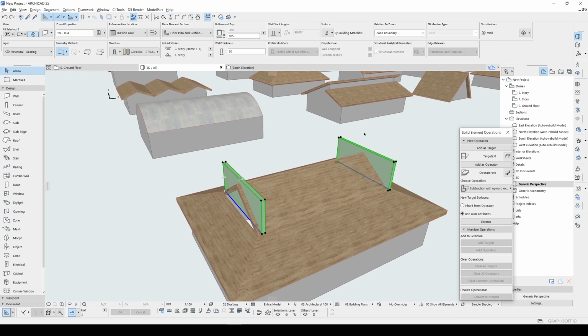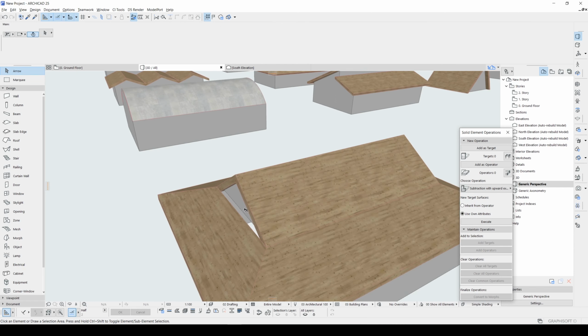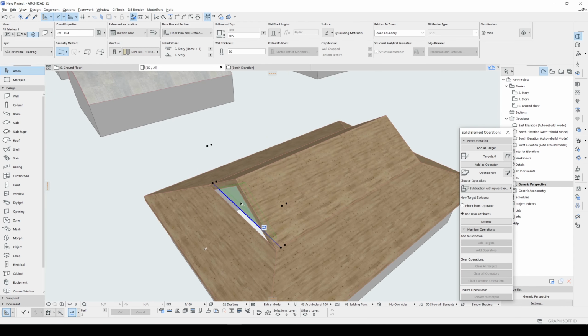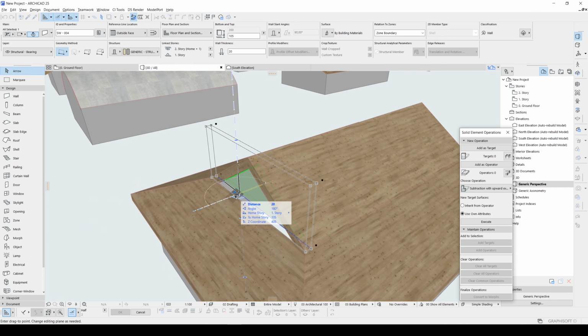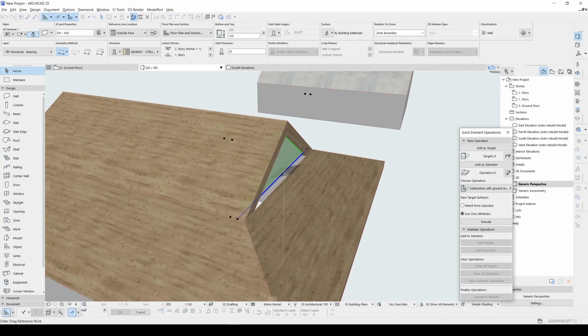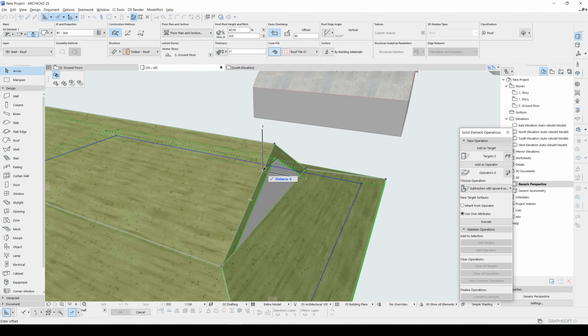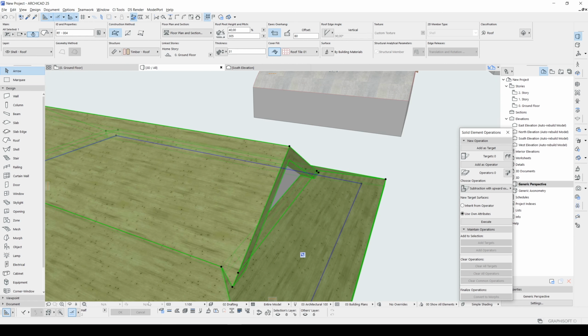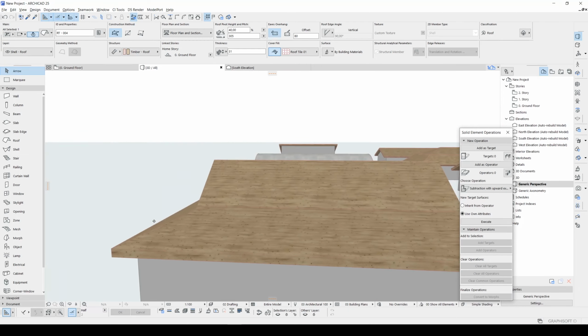Let's select our walls, right click, trim, click bottom part. And now as you can see, we have gaps here and also we have a gap. To fix it, we can move our walls and stitch to the roof edge. And instead of moving this wall to inside, we can extrude the offset gable overhang, maybe 40 centimeters. Or 30. Yeah, that's all.